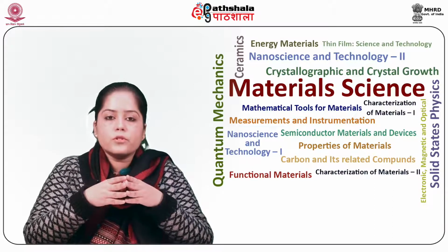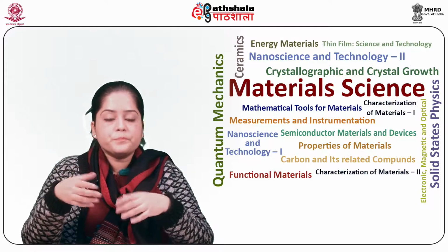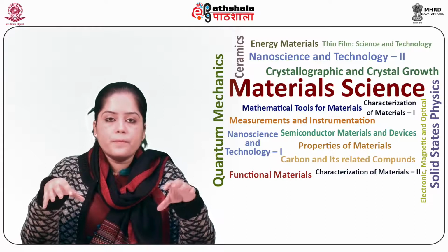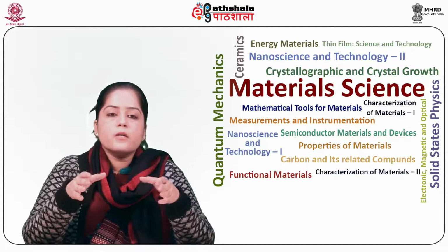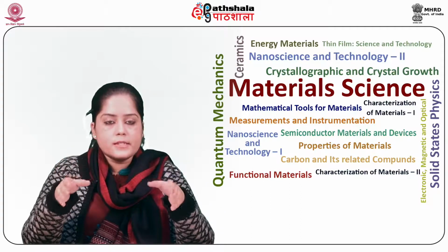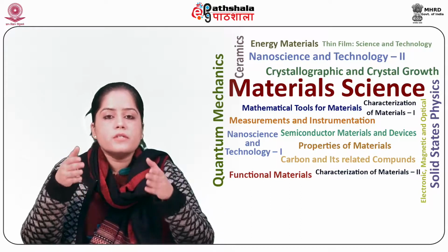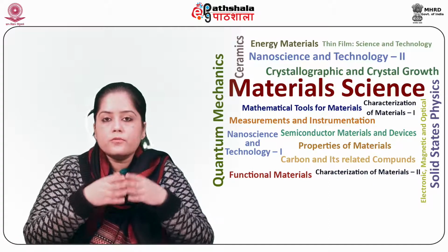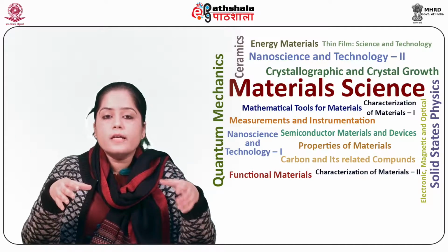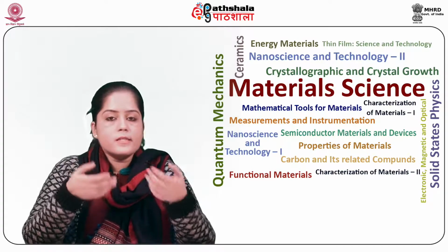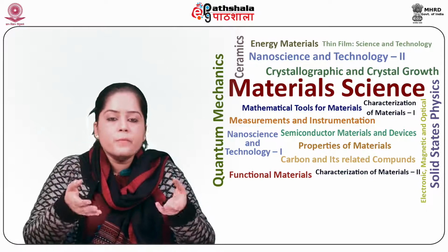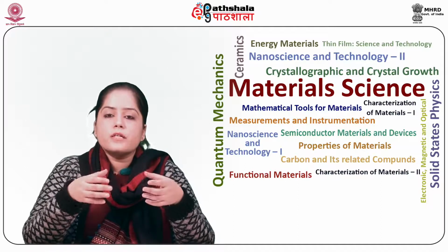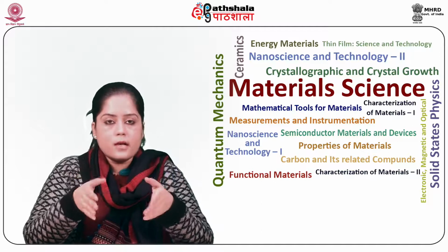Photoresist is primarily used for defining areas of interest, that is, where we want the material to be present or absent on a wafer. So the basic phenomenon includes coating the wafer with photoresist, which is then subjected to selective illumination through the photomask. After the initial patterning of the photoresist, other barrier layers such as polycrystalline silicon, silicon dioxide or silicon nitride can be used as a physical mask on the chip. A photomask is constructed with chromium-covered quartz glass.